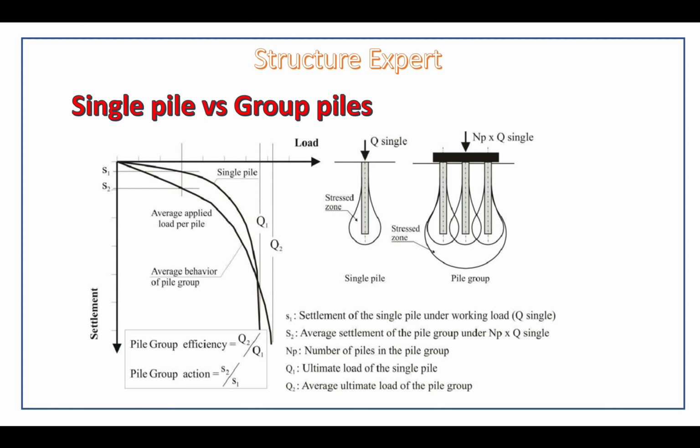It is the difference between single pile and group pile for the soil bearing capacity, but for calculating rebar it's not different. We just use the internal force to calculate the rebar, but the single and group pile effect on the bearing capacity of soil, you should remember.